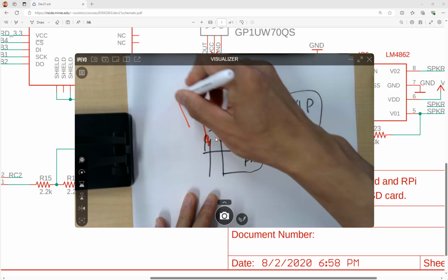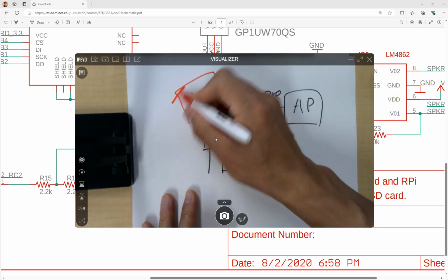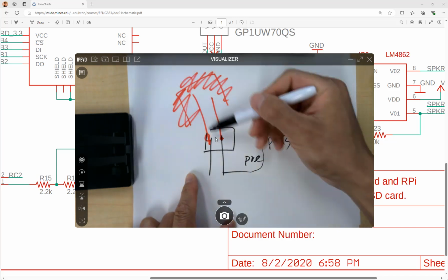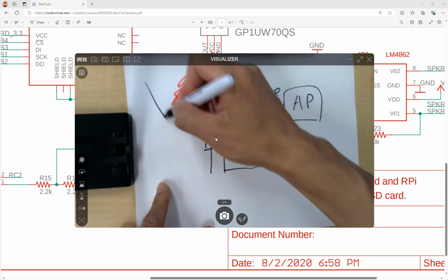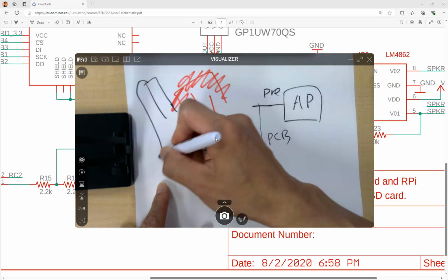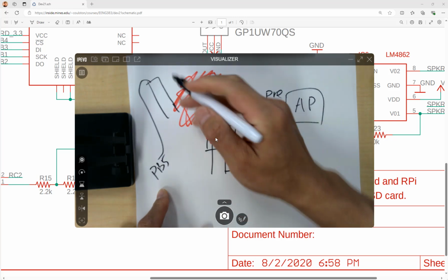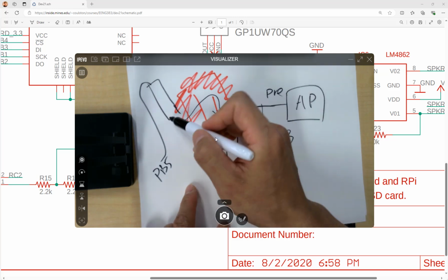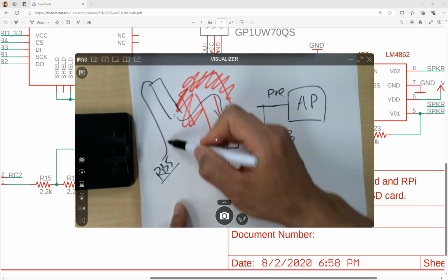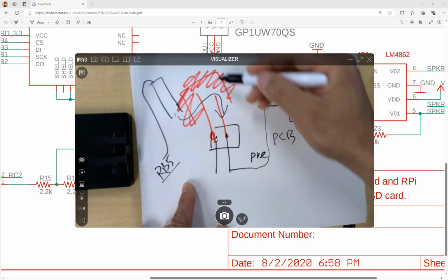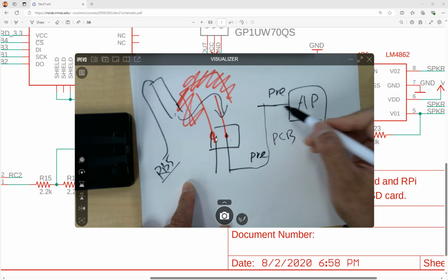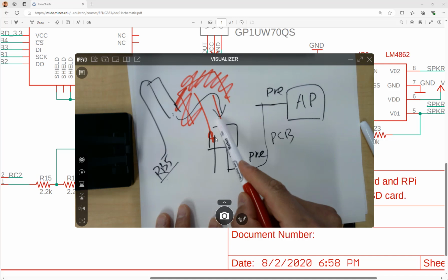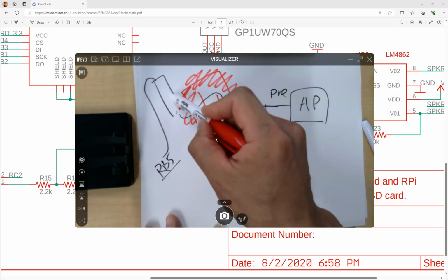Another header pin. Remember, you put a jumper here to make the connections. But for example, we don't put the jumper on the top. So what's happening is you have this header pin available, right? And you got a female cable here, connect to RB5. So we directly put this cable, connect to this male header, right? So the RB5 signal will directly be sent through this female header to this male header pin and directly get into the audio amplifier. That's how that works. You don't need a jumper here. If you have a jumper, there's no place to plug in that female jumper cable.